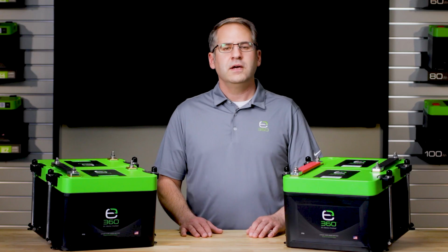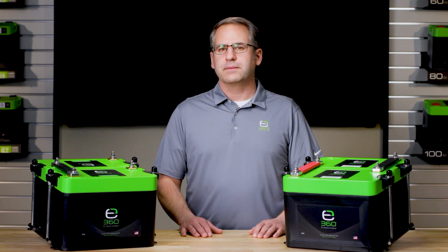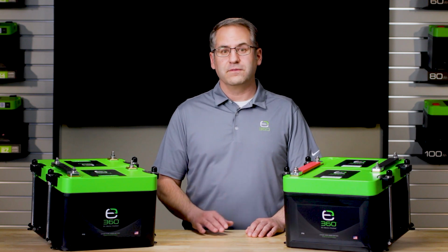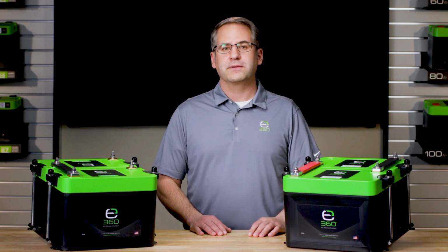Fuses will vary depending on the voltage and current of the application that they are protecting. There may be independent circuits that make up an entire installation that have separate fusing requirements. For example, the circuit for your 6-amp water pump might have an automotive DC type fuse that is rated at 10 amps, while the input fuse for a 3000 volt amp inverter charger could be 400 amps. In any case, it's important to use the correct fuse for a given application.